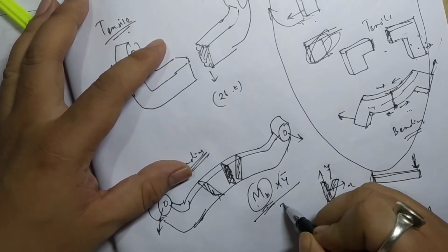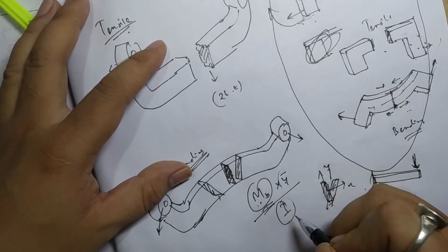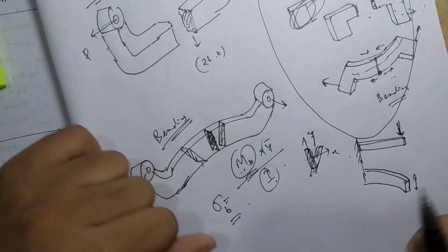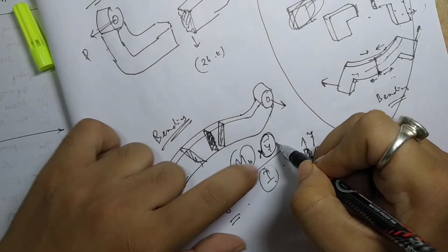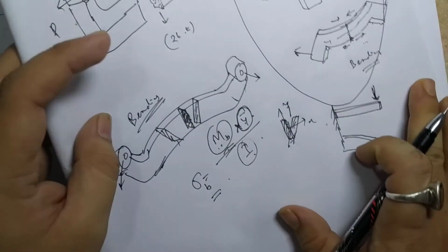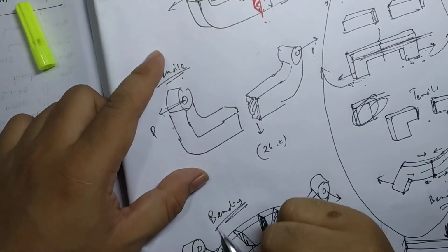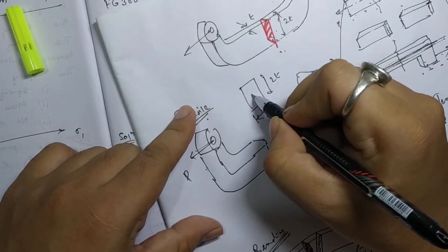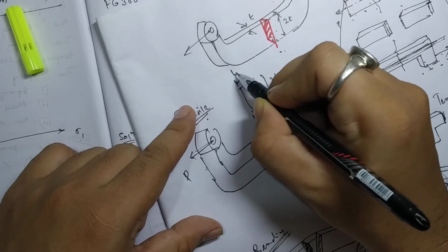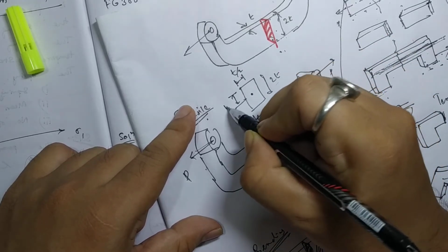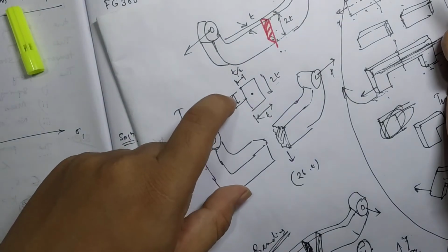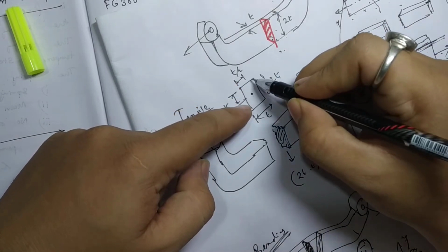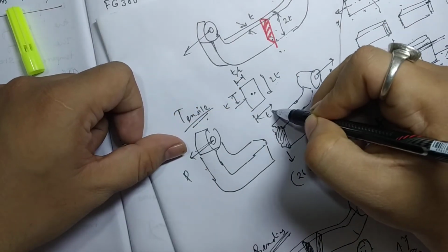So if you divide this MB into y bar by I, you get the bending stress. This y bar here is nothing but the centroid. Centroid means center of area, and center of area from which direction? By the way, this is the area, right? This is your t, and this is twice t. So the center will be here. Half from here to here is t by 2, right? From here to here is t. So your center of the area is located at t from, if you take the vertical direction, this is twice t, so this will be at t, the half position. This is t, so this will be t by 2.